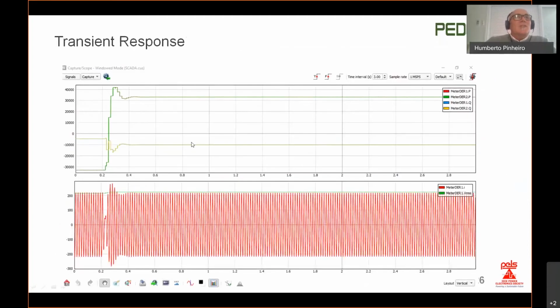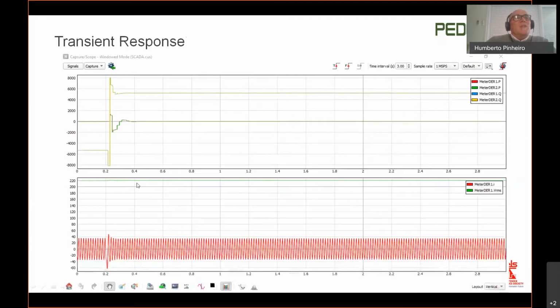This is a similar result over here, in a different time scale, where the power changed from 1 pu to -1 pu to 1 pu. We see that when there is this sudden change in the reference for the reactive power, the response is very fast. This is good somehow. But I expected 33 kVAr, and actually we are getting almost 5. So this had already been predicted by the steady state behavior.